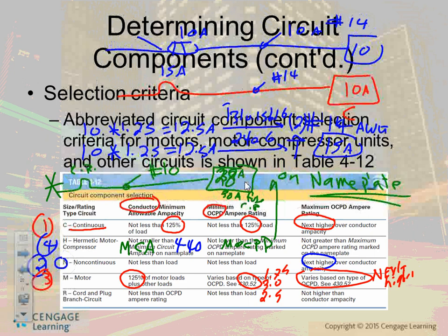A lot of 3-phase systems also use this. They say 208, 240, single phase, 3-phase motor. So you can power it at 208 if you want to, or 240, and it will accept it. Now, if you go to 480, you have to rewire it. So they allow you a range of voltages.